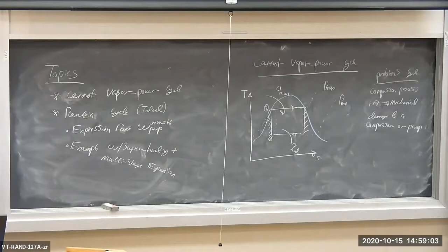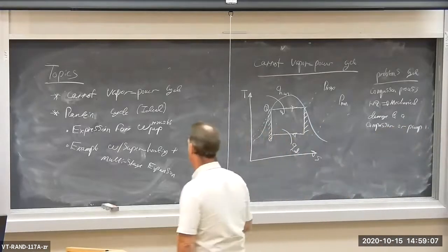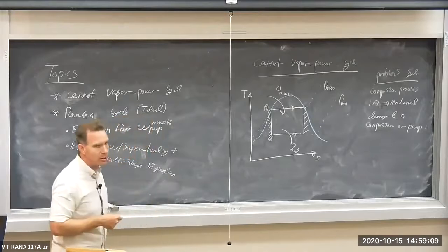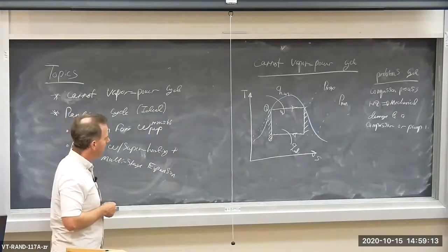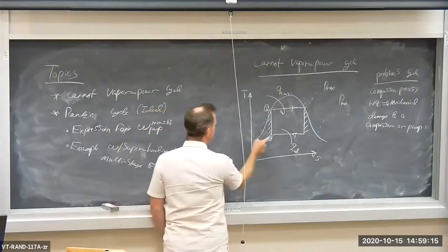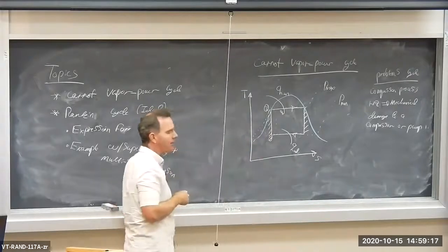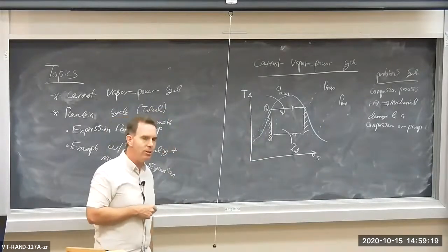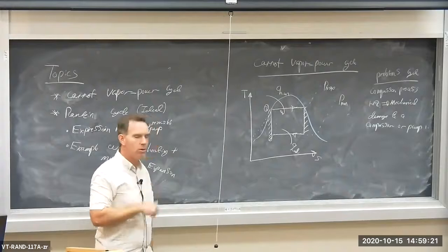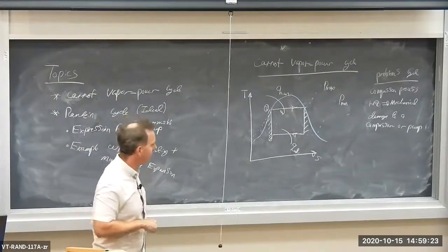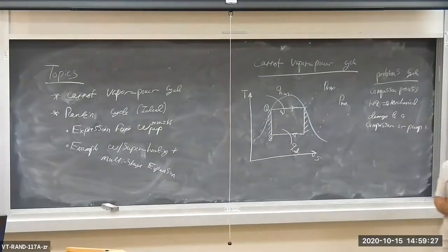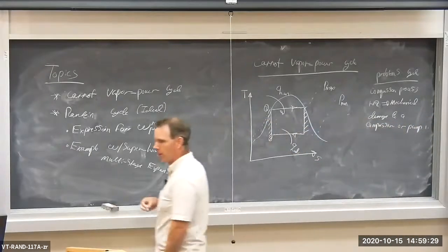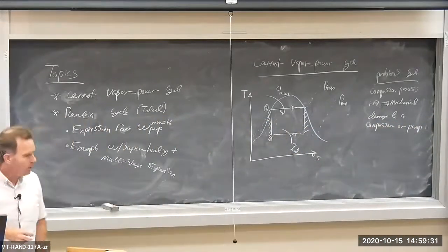So that's the primary objection. There are some other objections here, but they're not so bad. But that's the primary objection to this Carnot cycle within the saturation dome. The process 1 to 2, which is the compression process from P-min to P-max, it's not easy to develop a device which can compress a mixture of liquid and vapor up to a saturated vapor. Not easy to build such a device. Okay, so what are we going to do?